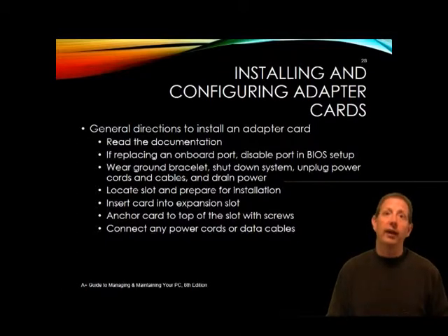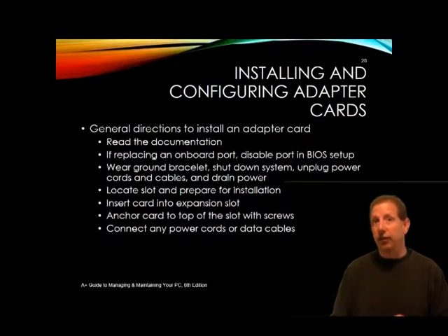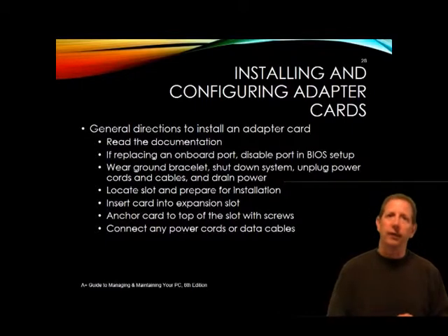Remove the card from its anti-static bag and insert it into the expansion slot. Be careful to push the card straight down into the slot without rocking the card from side to side. Rocking it can widen the expansion slot and then give you intermittent problems by not having good contact. If you're having problems getting the card in the slot, by all means, please resist the temptation to force it into the slot. Violence and technology do not make good bedfellows.